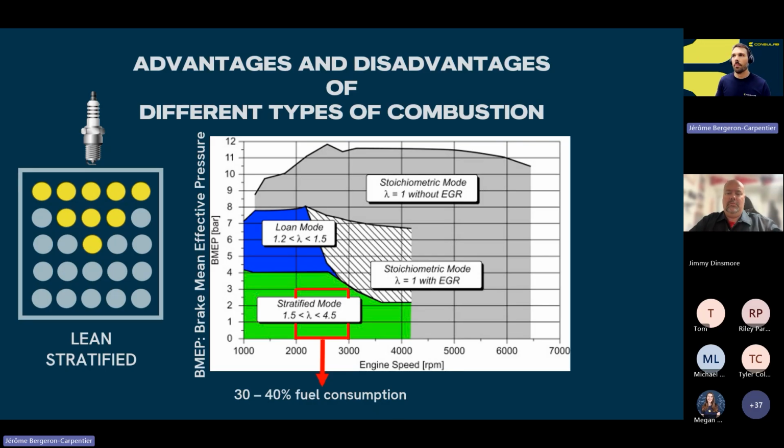You're going to see some PIDs like the engine temperature, because the carbon is going to warm up and absorb a lot of heat from the combustion, and it's going to create some super high heat zones in the engine, and you can see that with those PIDs. So like I said, engine temperature or engine coolant temperature, you're going to be able to see that definitely.